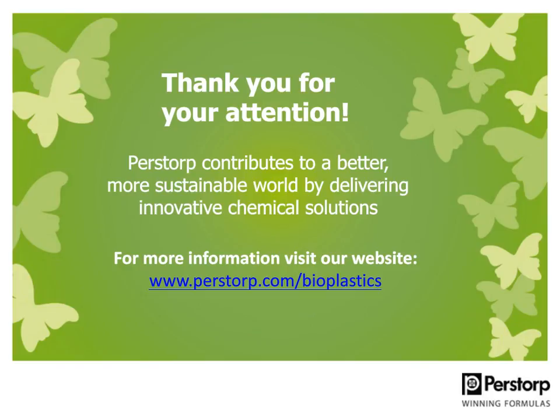Thank you. Next one is, what are the recommended processing temperatures for Capa when used as a master batch carrier? It really depends on the components that you use. We have prepared some master batches where we really processed them at 60 degrees. So you just about have to soften up the Capa and you can incorporate the pigments and the fillers or the calcium carbonate that you use.